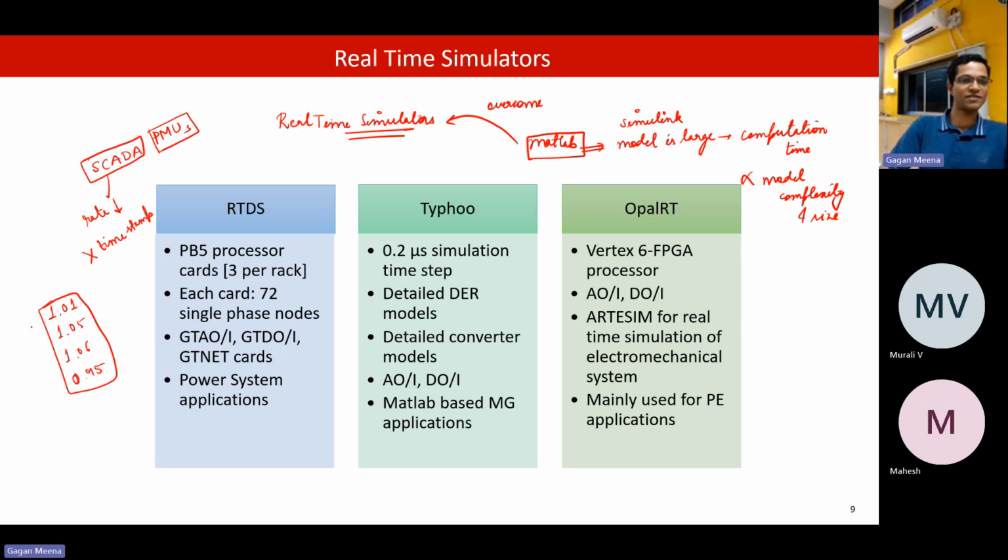We don't know what time this data corresponds to. And if we compare two data sets, let's say this is for bus 1 and this is for bus 2, and we want to calculate the power flow between a line connected between bus 1 and bus 2, then we need the information of this angle.